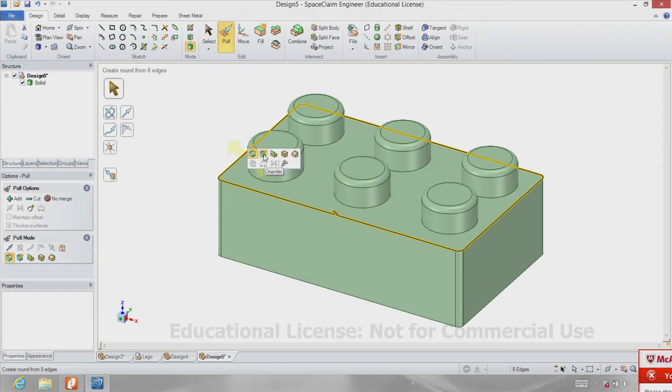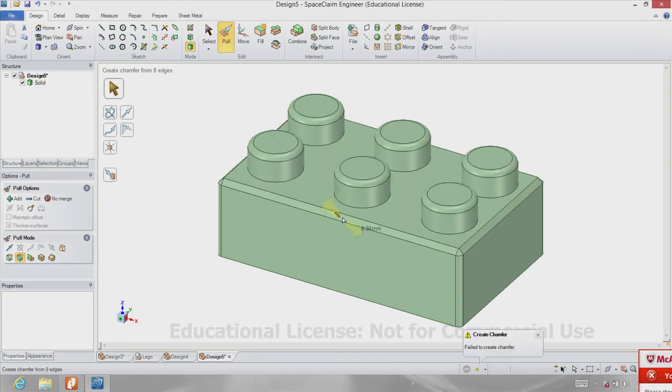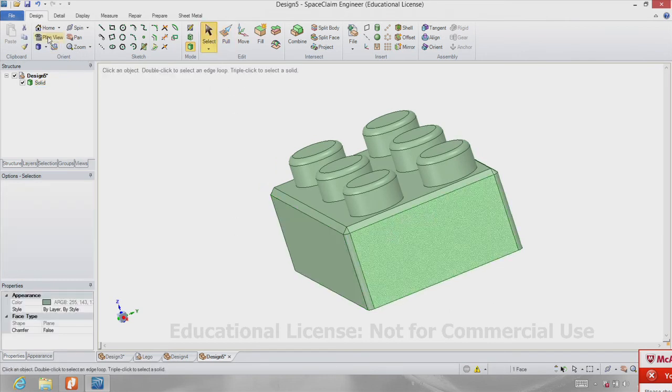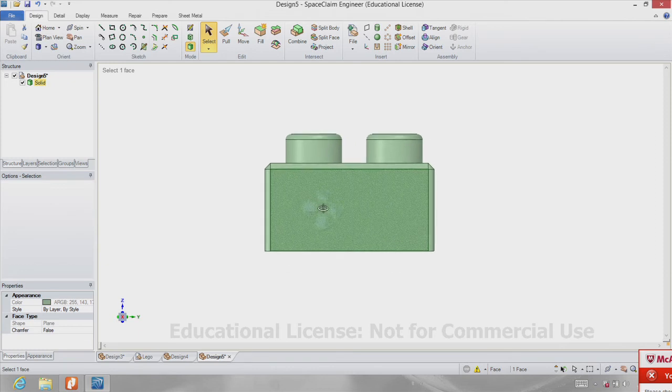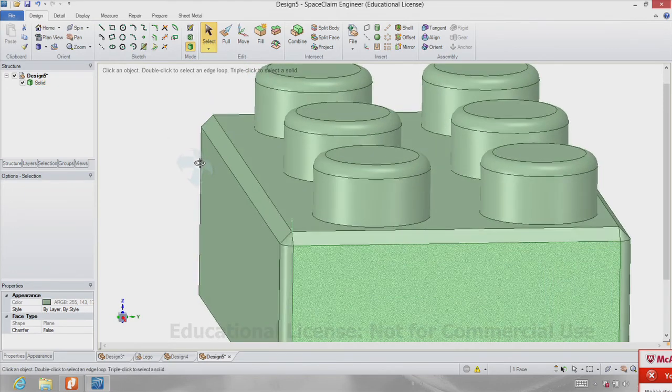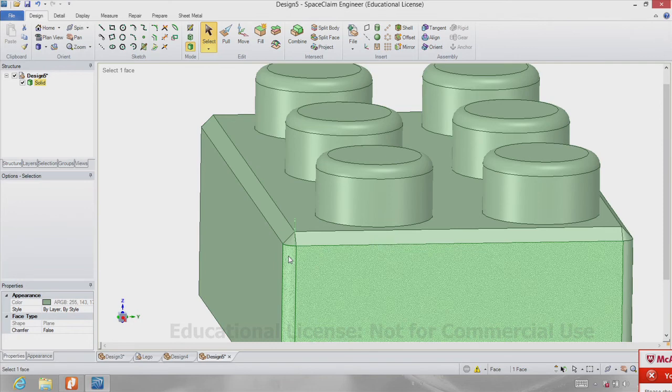The second option along in the dialog box here is chamfer, so I'm going to click on that. And now I'm going to push the arrow down, hit space, give it a value of 1 and hit enter. What you have done now, if I select the end view, you can see that we actually have cut that corner off, and that's what we call a chamfer, when it's a flat surface. These are rounds where they've gone in a round shape. A flat surface is a chamfer.